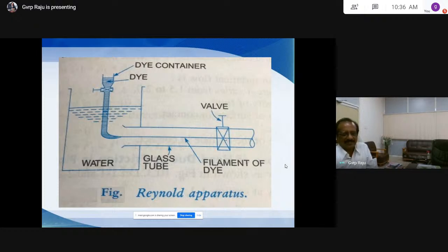Take three aspects here. So three are very, very important. Let us say the first stage, when the valve is open slightly. So then what happens here? The water which is there in the big tank starts moving into the glass tube and finally into the atmosphere. Then at the same time, this is a small tank here with the color solution. So I introduce this color solution here. This color solution, the purpose is to know the movement of water.